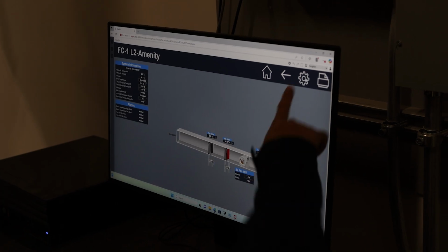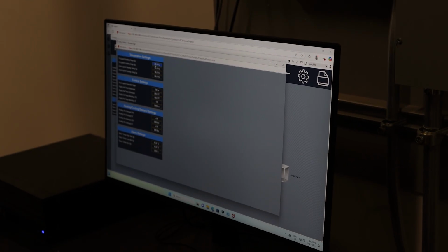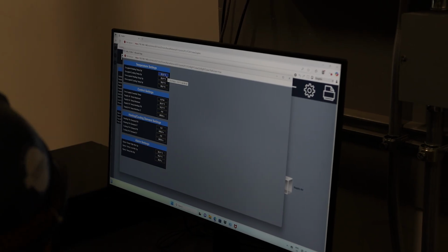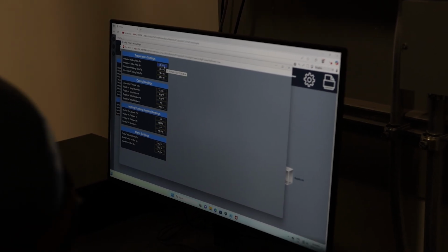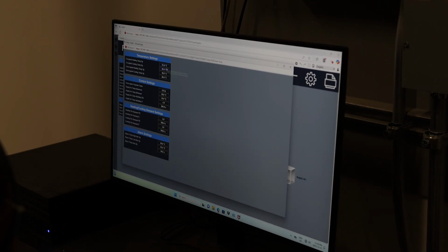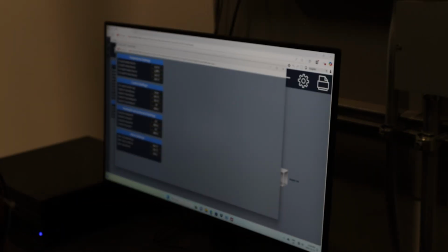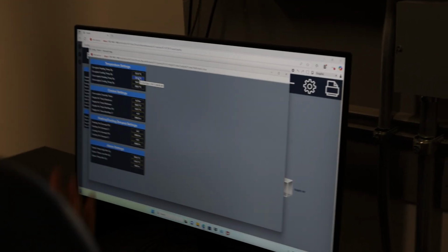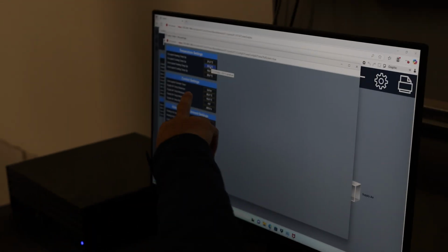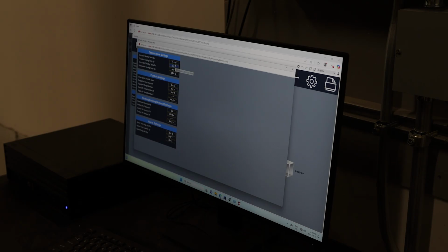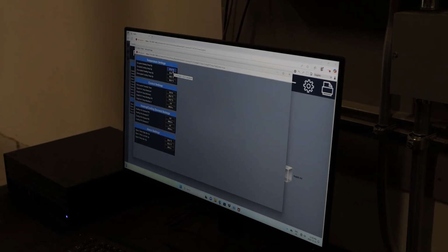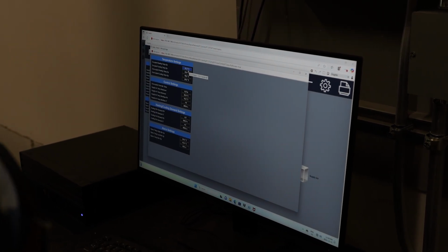If you click this setting button, here is the temperature setting. Occupied heating set point is 22. Occupied cooling is 23. That means in occupied hours, when space temperature is below 22, the heating turns on. This is now changed to 21, so if the temperature is between 21 and 23, there is no heating and no cooling. When space temperature is at 20, the heating will turn on.